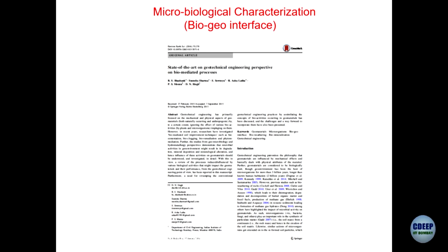This is another example of how to treat the leachates coming out of landfill. If I can use bacteria, and if this bacteria can survive in extreme pH conditions, I can mix or dose the leachates with bacteria-laden grains of geomaterials which will act as a seed to purify it, to bring down its COD and BOD.